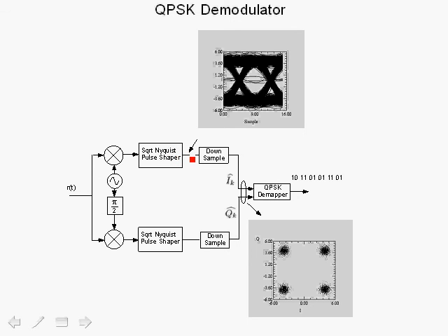And at this point we get the signal, for which we show the eye diagram with a channel with additive noise only, no multipath, and we sample at the maximum eye opening, and we receive the estimate I_k of the transmitted symbol. Similarly for the quadrature phase term, however in this case we multiply times sine of 2 pi Fc t. Again we get the baseband term and a double frequency term.